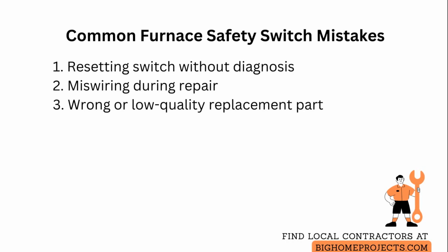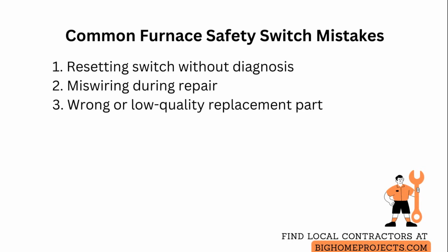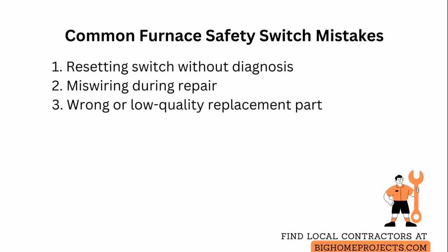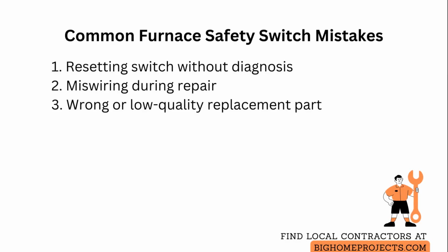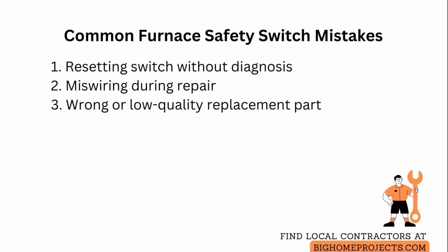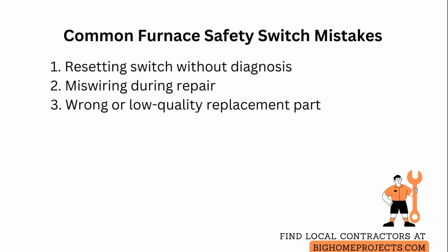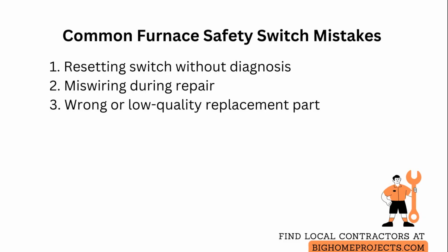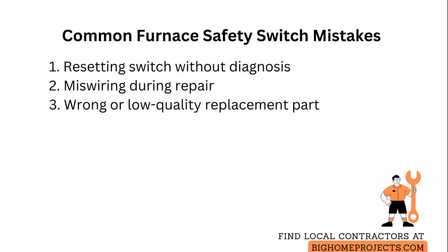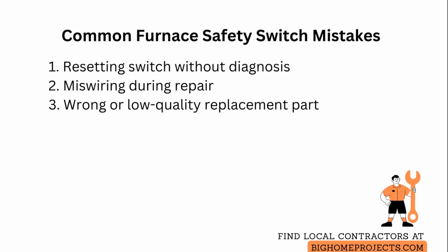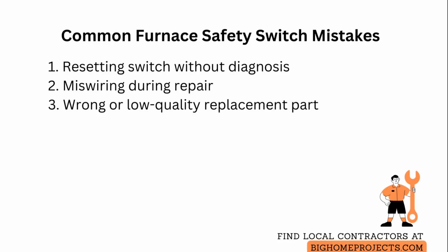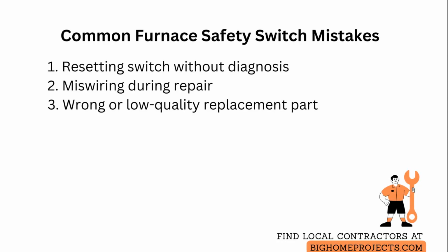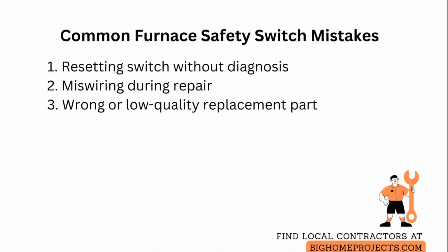Another frequent issue is miswiring during a repair, where the switch ends up bypassing the intended control path. So verify wiring against the schematic and correct any incorrect connections. A third problem is replacing the switch with an incorrect temperature rating, or a low-quality part which will trip too easily or fail to trip. Match the original specifications and use a durable replacement to ensure proper operation.